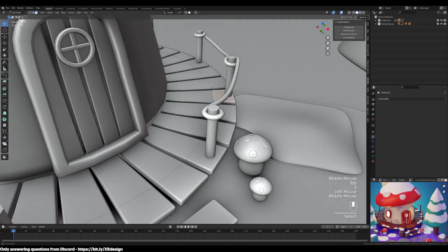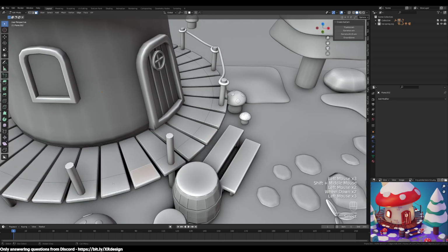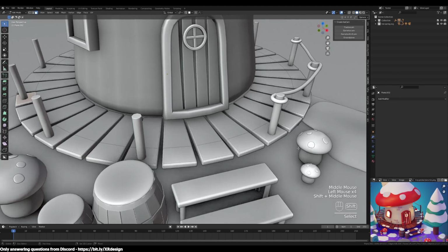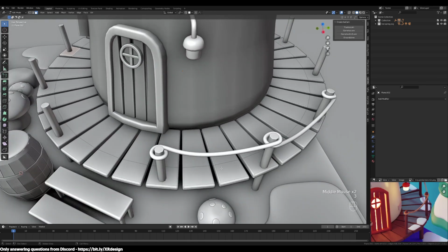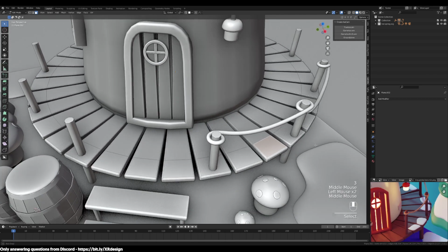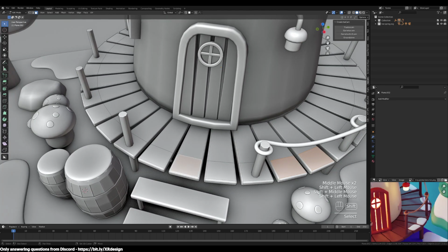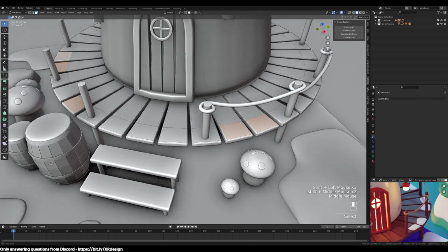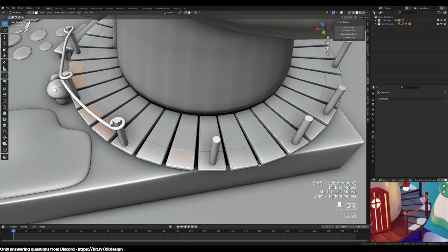And once you've done that, you'll notice that the same loop cut kind of shows along all of them. And maybe we want some variation to how far the snow is going in. Let's just copy a few of these. Let's duplicate a few. I'm just going to select the ones that aren't overlapping with the wooden poles here. So just selecting the two here, one here.